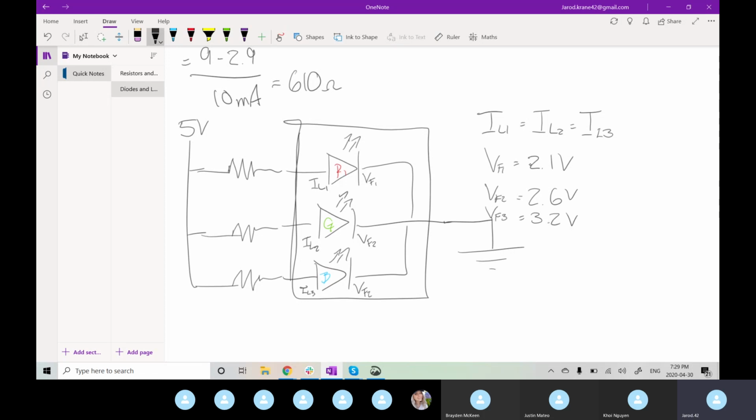They're all going to need a slightly different resistance to be able to have those all take in 5 volts but properly output 20 milliamps, or whatever the actual current limit is. But you can basically treat an RGB LED as several in parallel.